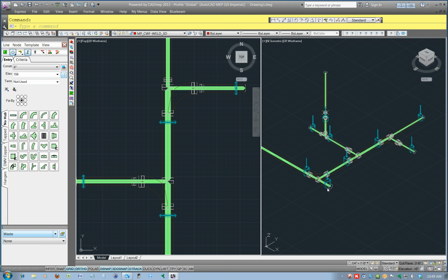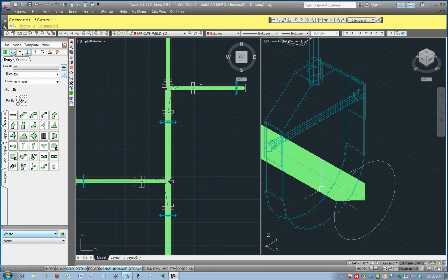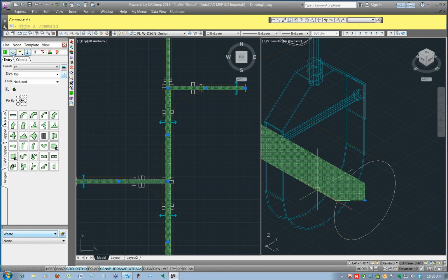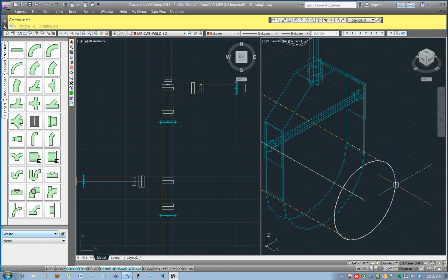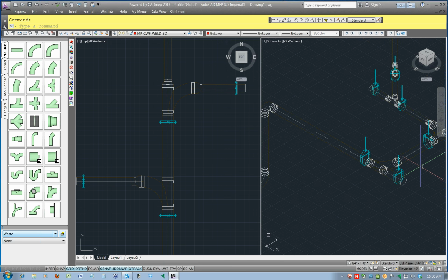I have to delete my extra pipe pieces like this here. It's just a pain. So what I normally do is I just delete my design line after I pitch it. Like I said, with ductwork or maybe even with water lines, since they're not pitched, it'd be more worth it to leave that design line in there.